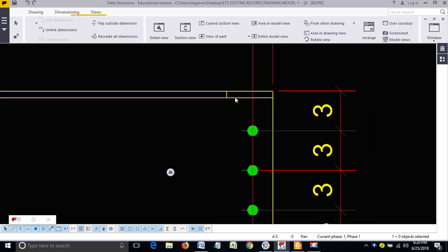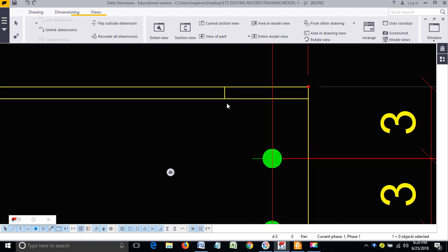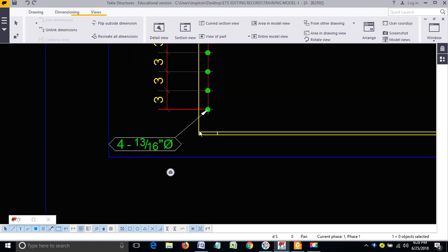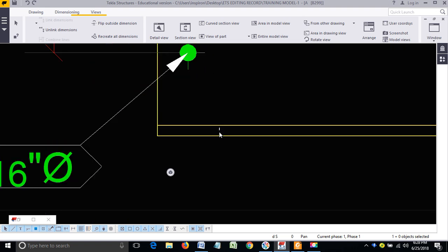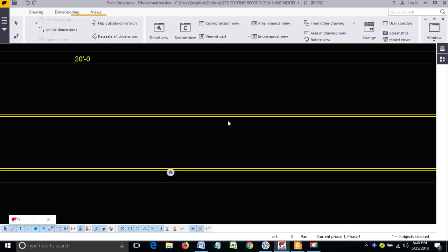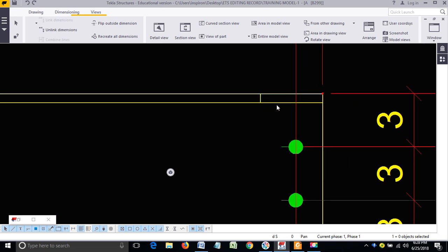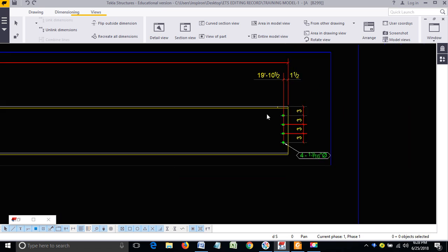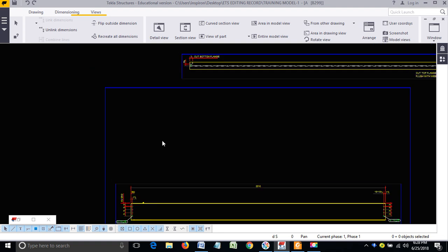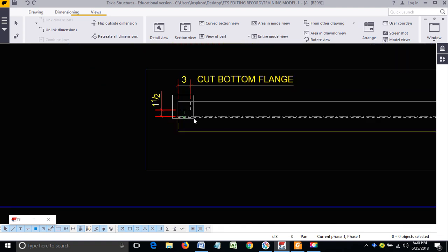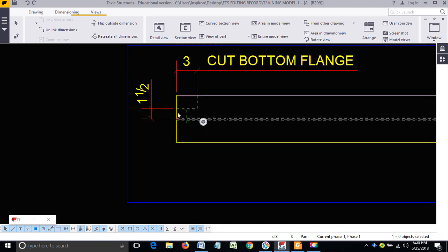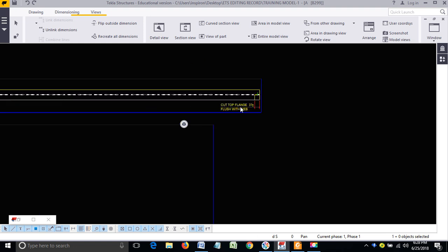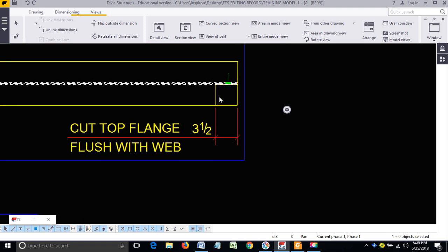something cut has happened. See, here is top flange near side, here is bottom flange far side, that's why it's coming dotted. Here it is coming continuously, means what you understand, near side. Okay, so this one front view we can't cover, compulsory we have to give top view because it is offset. This one sometimes we can cover in front view also. How we can cover, I'm going to explain now.